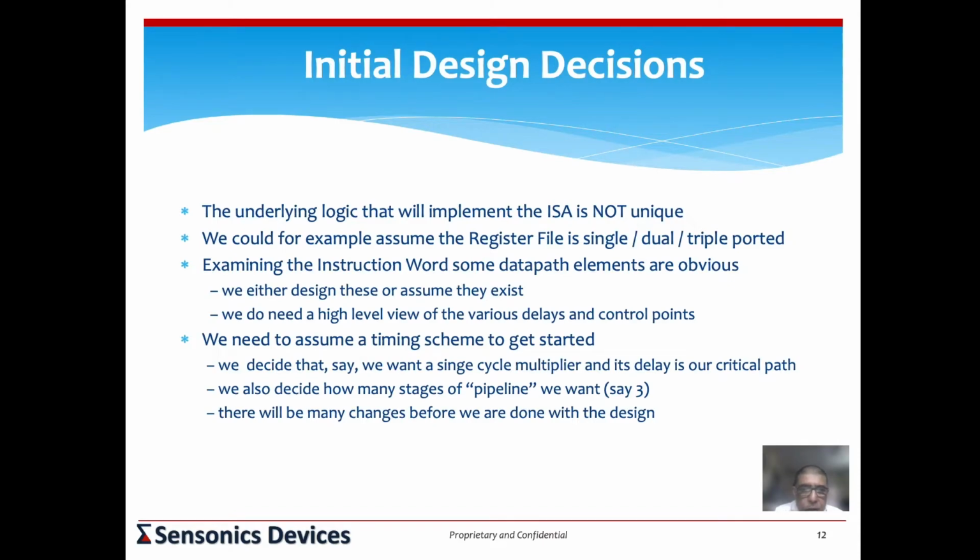So the ALU has the data ports as well as the control points. The ALU will have two sources. It will have one output. And there'll be a whole bunch of control signals that will tell whether you're going to perform a logic operation, arithmetic operation, whether the arithmetic is 2's complement or integer or things like that.